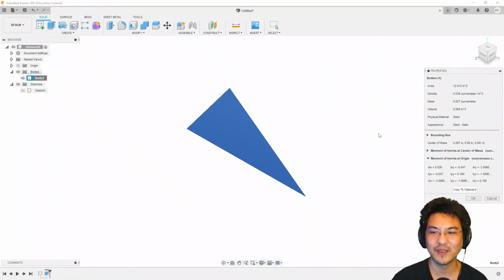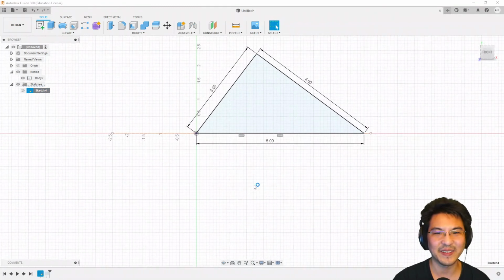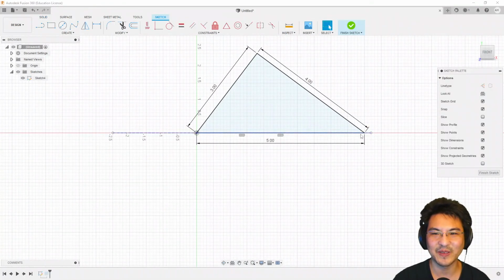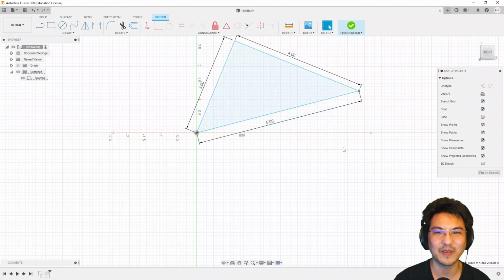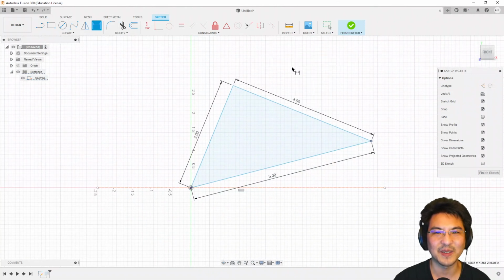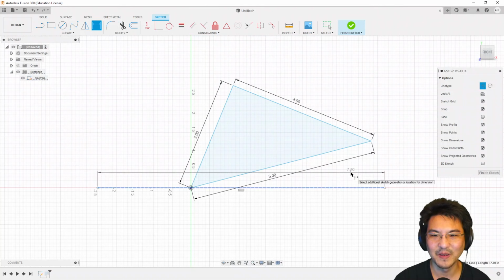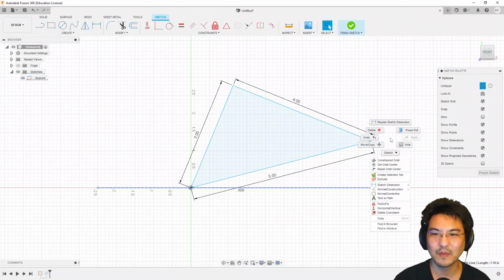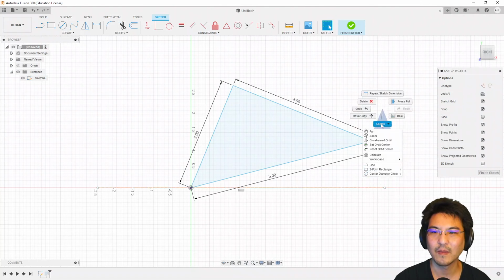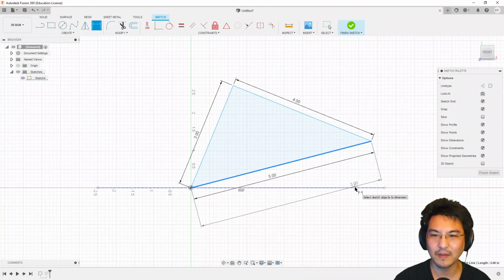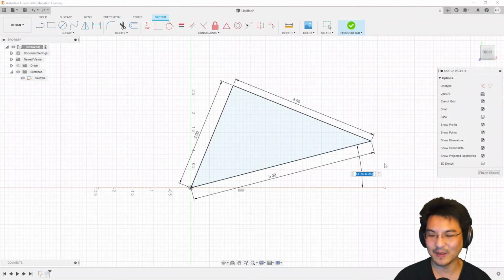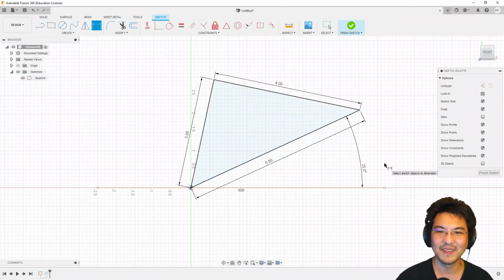Use those values to solve for the angle where you would need to rotate the coordinates to get principal axes. Once you have that angle, let me go back. I'm going to edit this sketch. Okay, so I'll make sure this is no longer horizontal. So see, I can rotate my triangle again. And then I'm going to dimension it to be whatever angle you need, whatever the angle was supposed to be, and there.